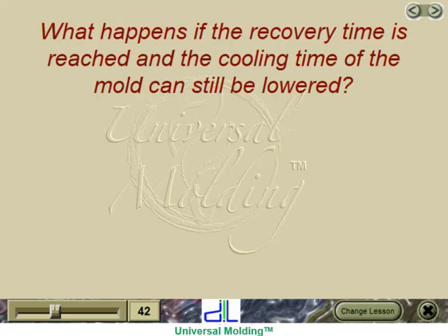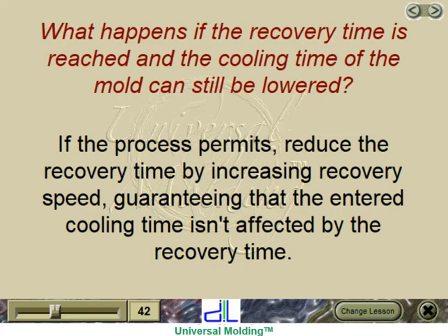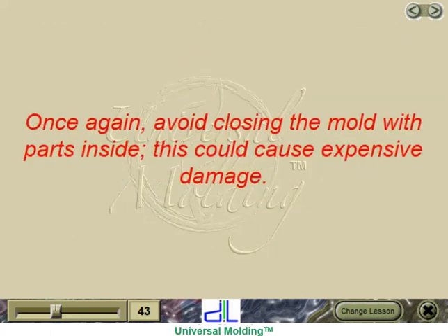What happens if the recovery time is reached and the cooling time of the mold can still be lowered? If the process permits, reduce the recovery time by increasing recovery speed, guaranteeing that the entered cooling time isn't affected by the recovery time. Once again, avoid closing the mold with parts inside. This could cause expensive damage.